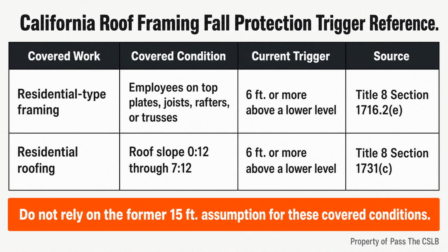The middle and upper placement of a rafter tie is not a casual headroom adjustment. Once the tie moves above the bottom third, the prescriptive roof triangle is no longer the governing solution. A structural ridge beam and an engineered support path are required. Even inside the bottom third, raising the tie increases heel joint connection demand, so the fastening schedule must be adjusted rather than guessed. When I review this work, I ask 4 practical questions.